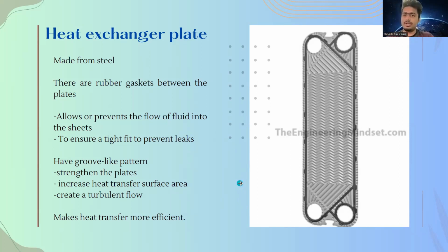Then the heat exchanger plate has a groove-like pattern, which strengthens the plates, increases the heat transfer surface area, and creates a turbulent flow, which makes heat transfer more efficient. Next.